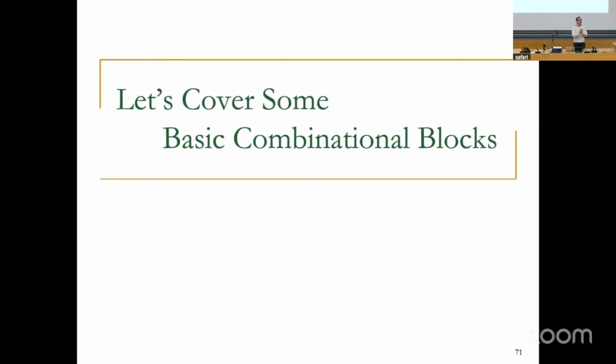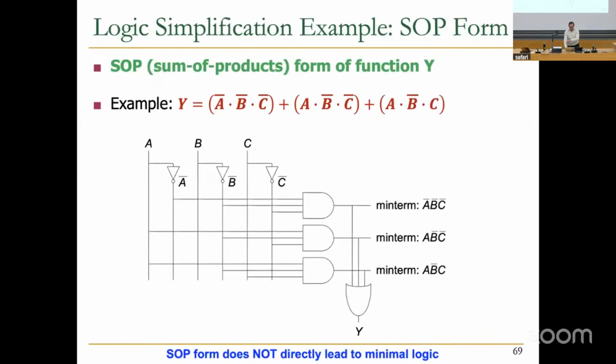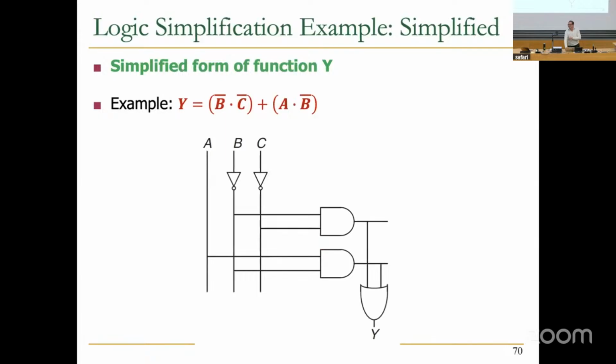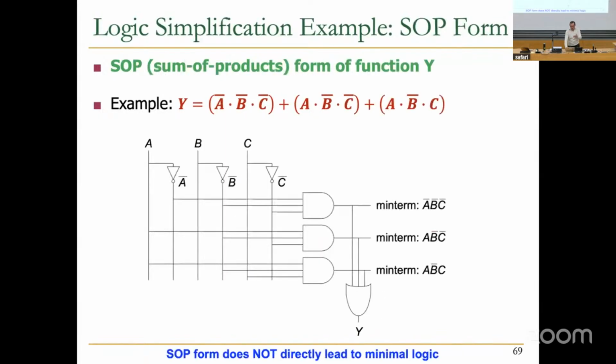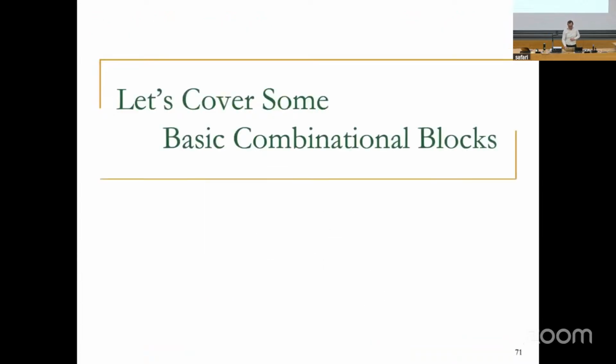Minimizing the circuit is good for reducing area. It could be good for reducing latency. So going from here to here, clearly less area, right? Probably less latency, based on what we have seen. But you do lose some redundancy in the circuit. Maybe if there's an error in one of the bits, you will not be able to tolerate it, or you'll tolerate it less. Okay? And with timing, we will see something else when you do the timing analysis.